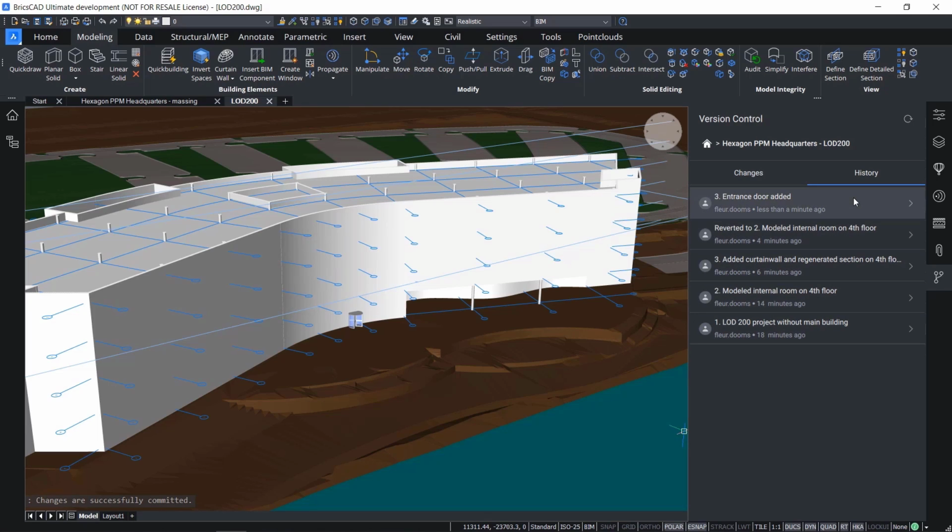Also good to know when reverting is that if you revert to an older commit, you will lose access to the latest work in progress drawings, as they got overwritten by an older commit. So if you wanted to save that state as well, make sure that you did a new commit just before reverting to an older version. If you're not happy with the file you chose to revert to before you made the reverted to version X commit, know that it's always possible to just revert to another commit as well, maybe even to the latest one you made.